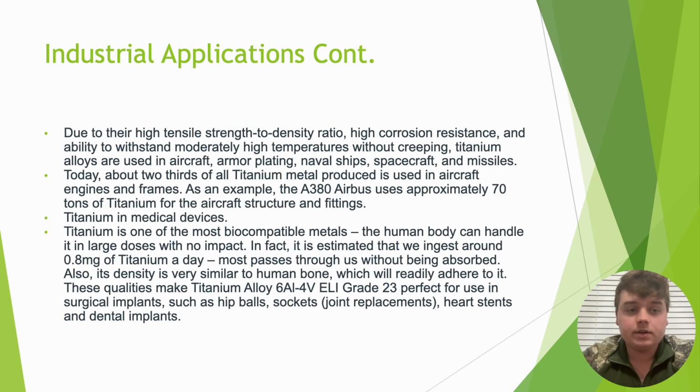Industrial applications continued. Due to their high tensile strength to density ratio, high corrosion resistance, and ability to withstand moderately high temperatures without creeping, titanium alloys are used in aircraft, armor plating, naval ships, spacecraft, and missiles. Today, about two-thirds of all titanium metal produced is used in aircraft engines and frames. As an example, the Airbus A380 uses approximately 70 tons of titanium for the aircraft structure and fittings.